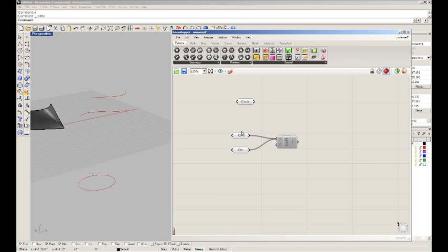In Grasshopper, information flows left to right, and to the left is considered upstream and to the right is considered downstream. So everything is moving left to right. So everything downstream or to the right of this loft would not work if I had it disabled. And there are different reasons that you would use these at different times. Just note also that when something is disabled, the entire parameter or component is grayed out.